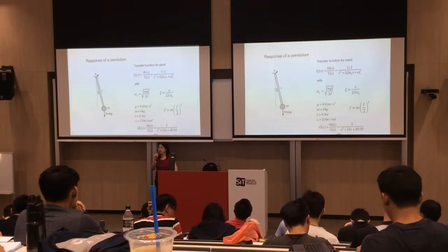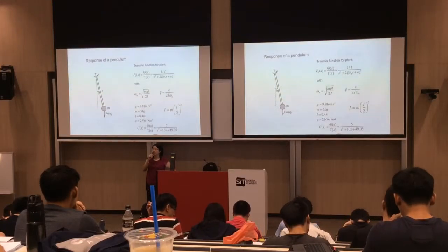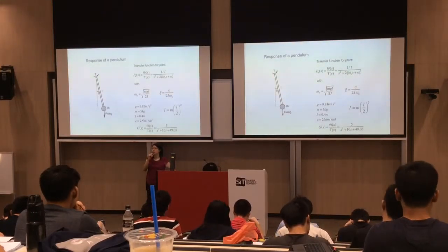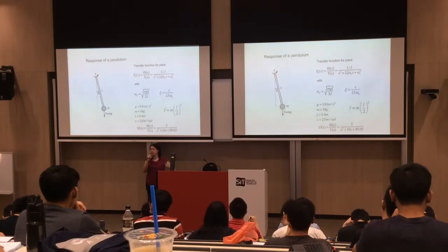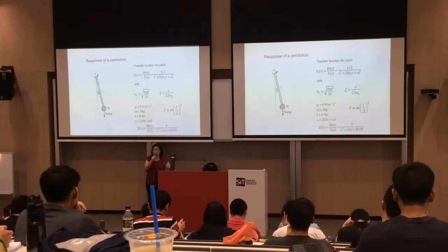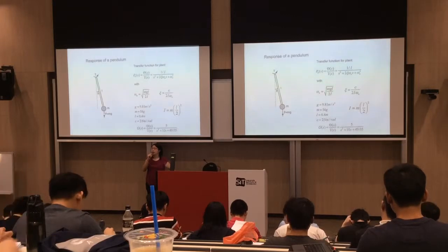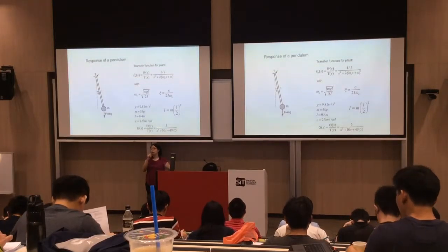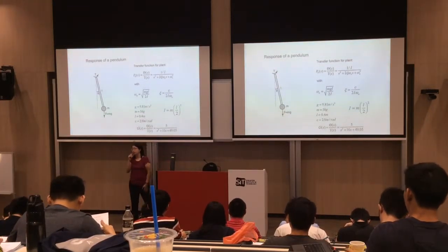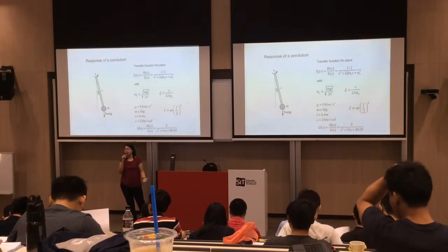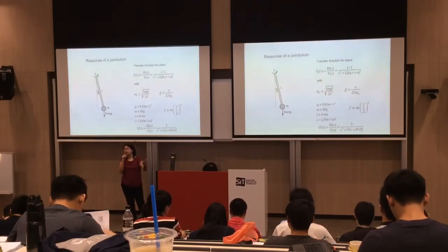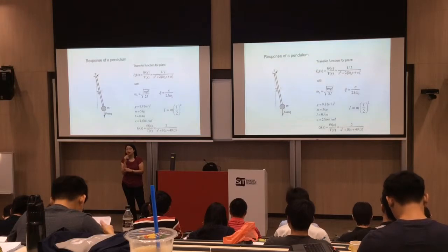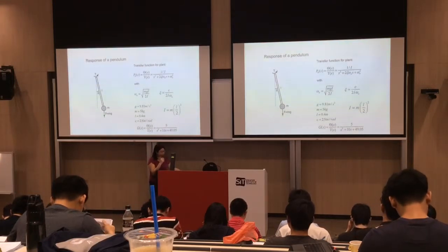If you work out the transfer function G(s), what can you do with it? Based on your understanding of dynamics and control theory, with this transfer function we can draw this plot by substituting different values. S equals j omega, you put in omega. We can work out the gain and the phase, and you can draw this one. Next, what can you do? You can convert the gain into dB. Alright, you can plot the Bode plot.